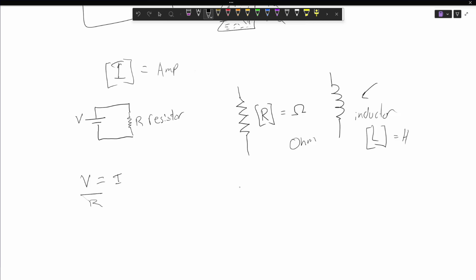And just like with capacitors, where we're also interested in talking about the energy, we'll talk about energy with resistors, but resistors have to deal with the flow of energy, not the store of energy. So the rate that energy is spent, the power. And so power across any circuit element is P equals IV, the current through that element times the voltage drop across that element. And so if you do some substitution with Ohm's law over here,